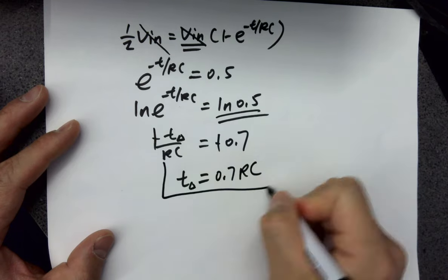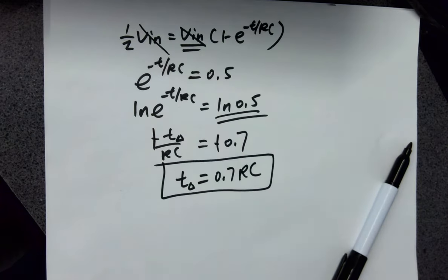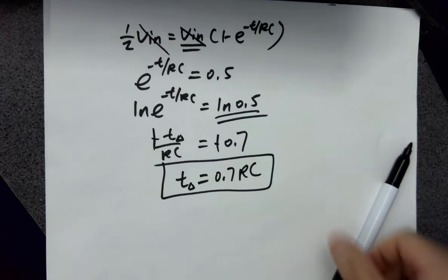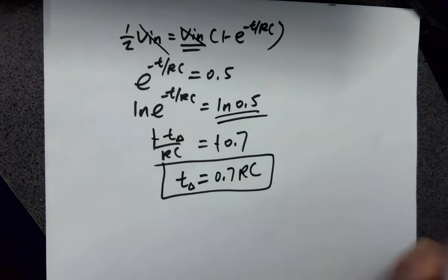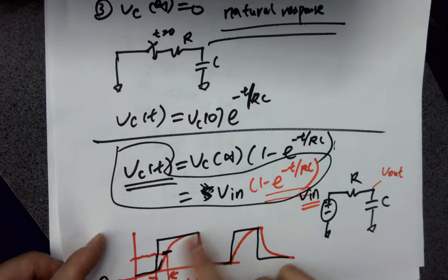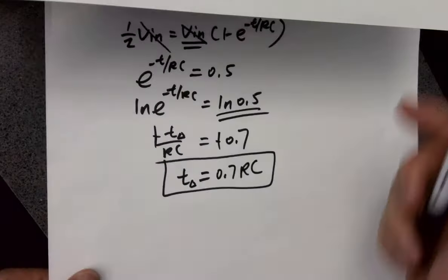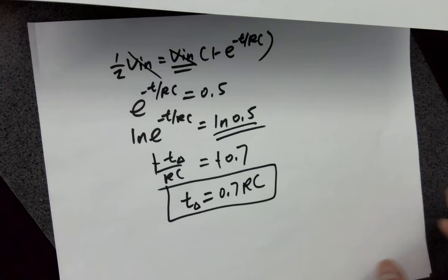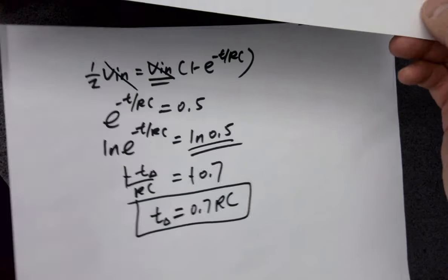So that's a conclusion, right? Digital circuits. Doesn't matter what the voltage is. It could be 100 volts, could be 10 volts, doesn't matter. So the time delay for digital circuits, as long as it's for charging up the output, becomes 0.7 RC. Very important conclusion here.